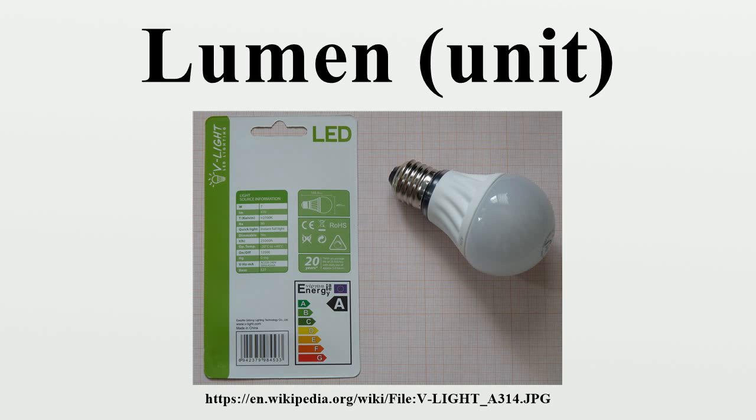On September 1, 2010, European Union legislation came into force mandating that lighting equipment must be labeled primarily in terms of luminous flux instead of electric power. This change is a result of the EU's Eco-Design Directive for energy-using products. For example, according to the European Union standard, an energy-efficient bulb that claims to be the equivalent of a 60W tungsten bulb must have a minimum light output of 700 to 750 lumens.